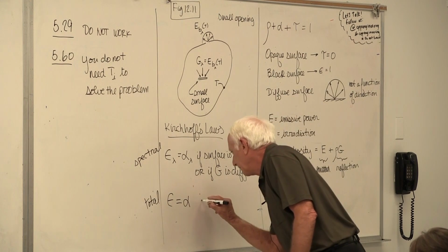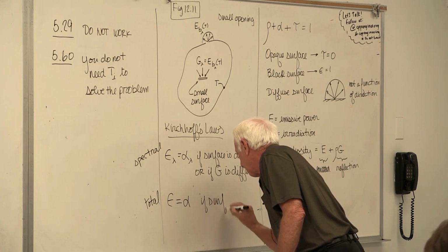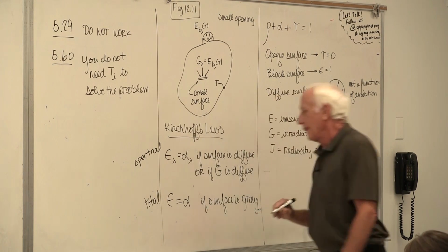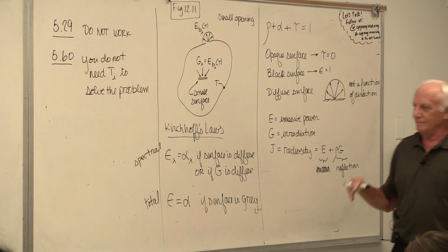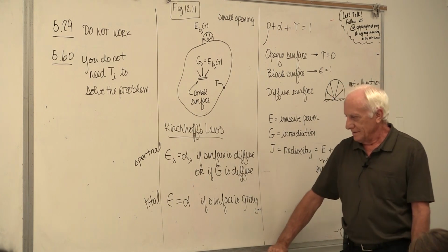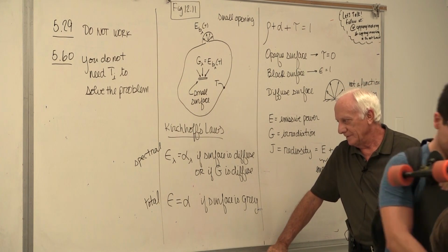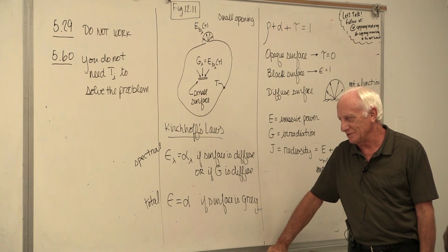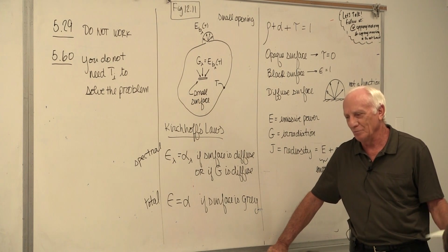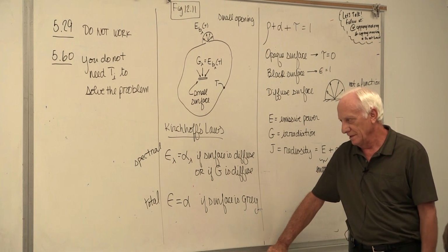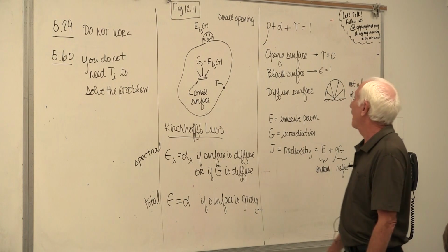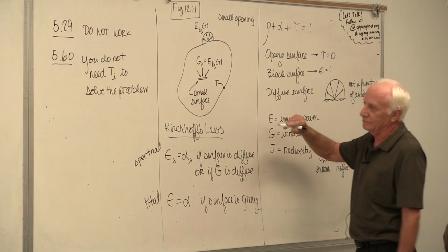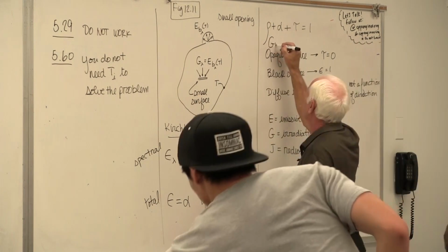That gives you what we call the total emissivity or the total absorptivity. That's true if the surface is gray. There's another qualifier there too: if the incoming radiation appears to have come from the same temperature as the surface, but that happens rarely, so the one we're interested in is this reason. Okay. Opaque surface, black surface. Now we have another one, chapter 12, gray surface.